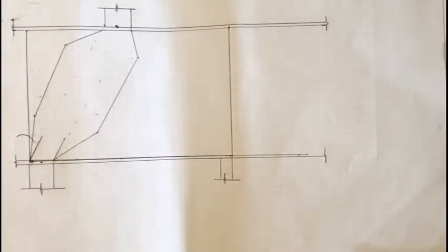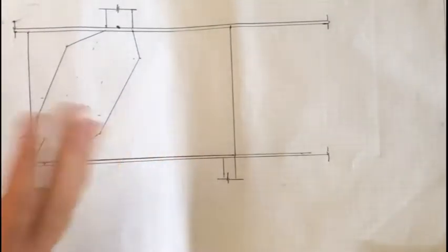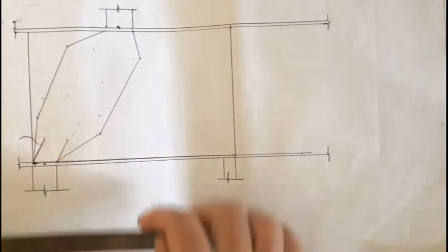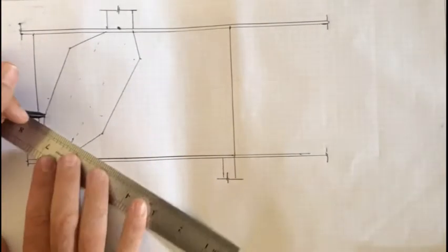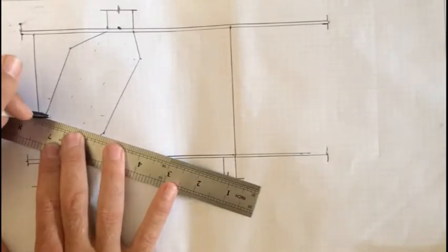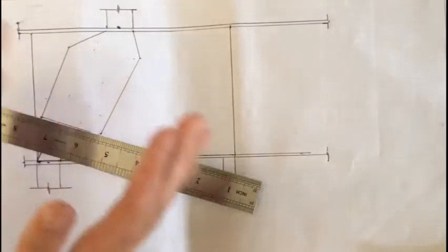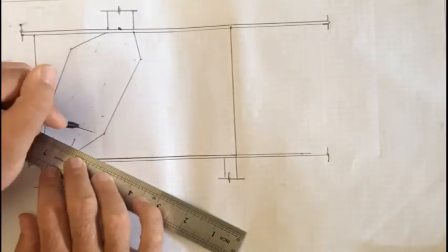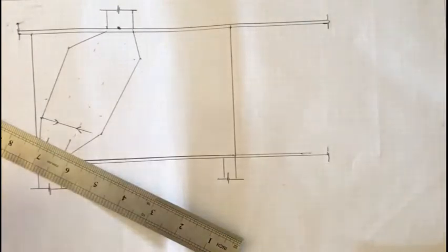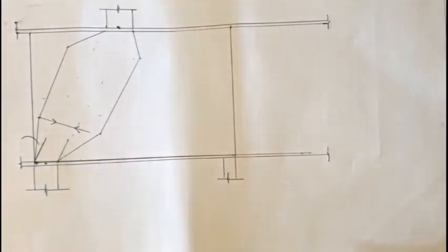So here, as it moves out like that in the bottle-shaped strut, you'll also have a tensile force here. So in between these axes, as it's pushing out, we have tensile forces developing. And if this tensile force is greater than the tensile strength of the concrete, then we need reinforcement to strengthen up the wall and reduce the cracking.